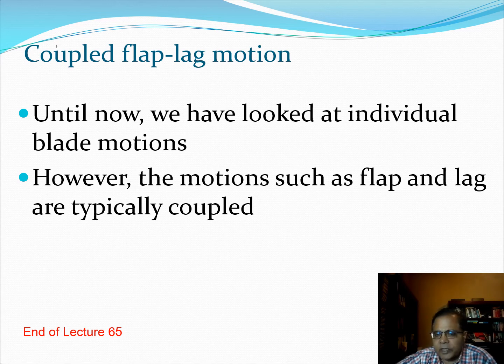So in the next couple of lectures, we are going to look at the genesis of this Coriolis term, which comes in the flap lag equations, because of which these flap lag motions get coupled. And then we are going to explore the coupled flap lag equations. In fact, one of the reasons helicopter dynamics gets complicated is because of this coupling in the equations, which is present because of Coriolis terms.